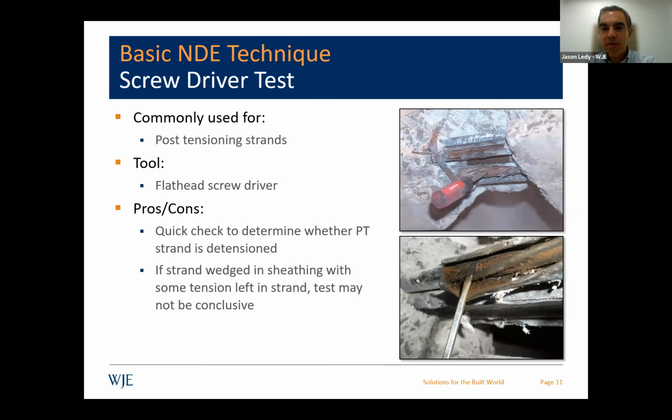So another fairly inexpensive tool is the screwdriver. In this case, the screwdriver test is being used to evaluate individual wires in strand, PT strands. There is some limited, as I mentioned earlier, localized destruction as you're creating the opening in order to expose the PT strand.